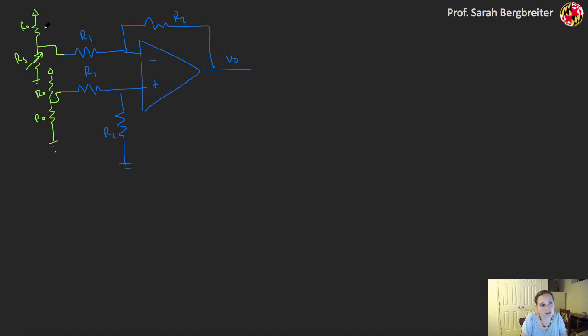So if I wanted to hook that up to some kind of voltage divider that I've used to measure a resistive sensor, so maybe this is a thermistor, maybe it's a light sensitive resistor, and I have an R naught here, and so I have this set up so that when this is R naught, I should get 0 at the output, but as this sense resistor changes, I'll get a different input there. But because I have this potentially small input impedance, I can have some pretty significant loading on this circuit, depending on what this nominal resistance R0 is here.